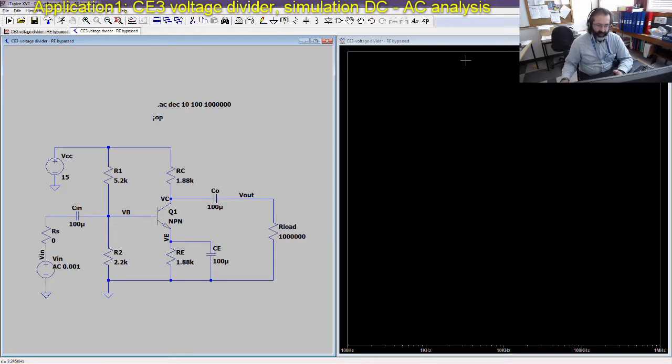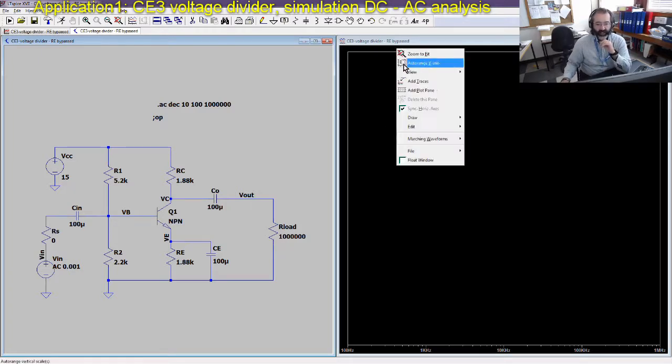So the first thing to check, since we have the series resistance is 0, and that's how we always did it in all our AC analysis, we always assumed that there was no series resistance from the generator. So I'll keep that at 0, and we will keep the load very large for now to simulate an infinite output resistance, an infinite load, so that now we can calculate the voltage amplification with the simulation I've just run.